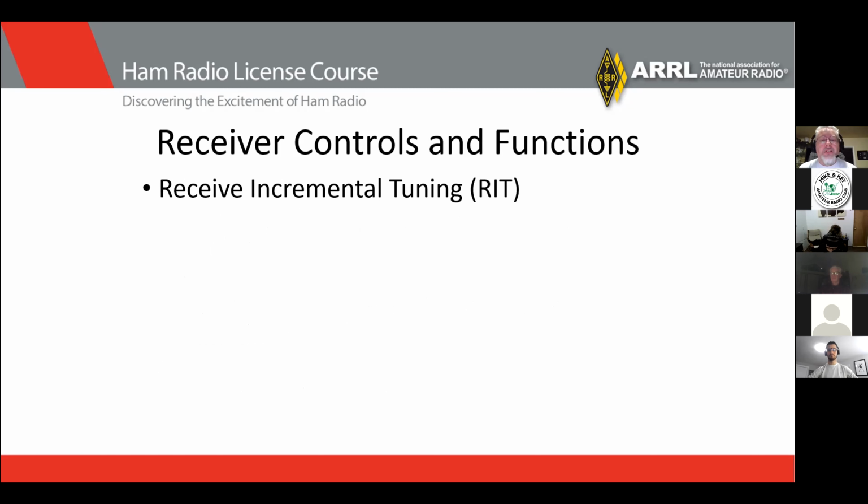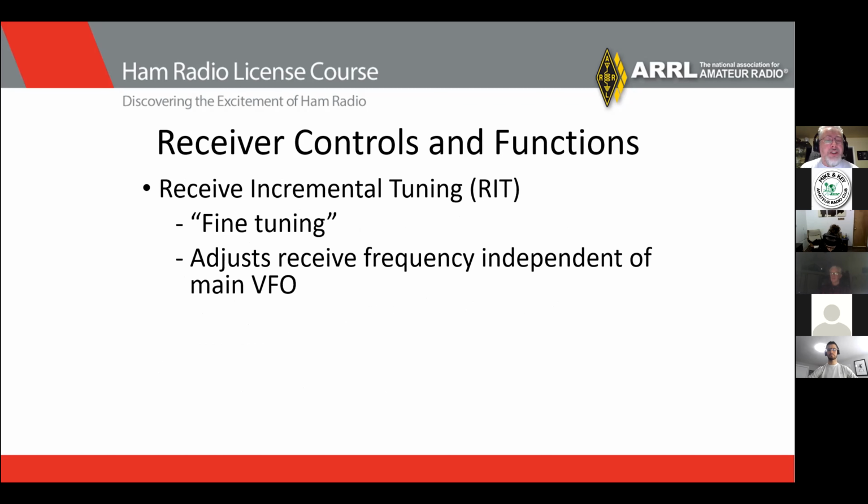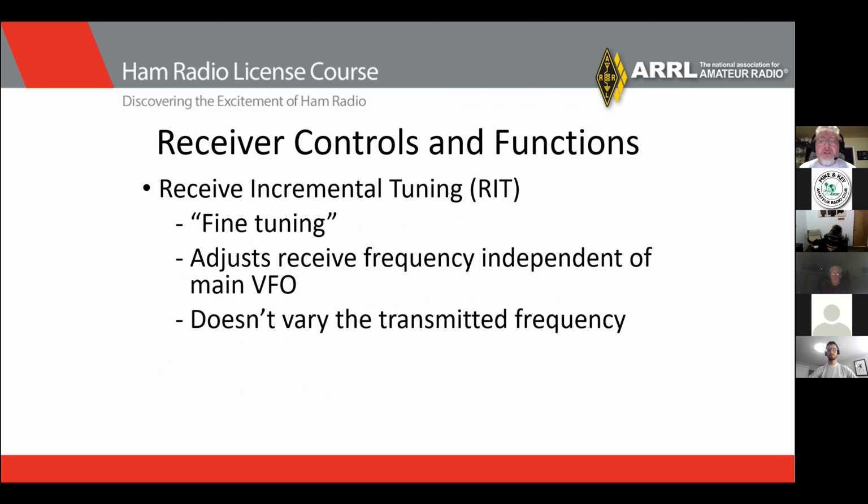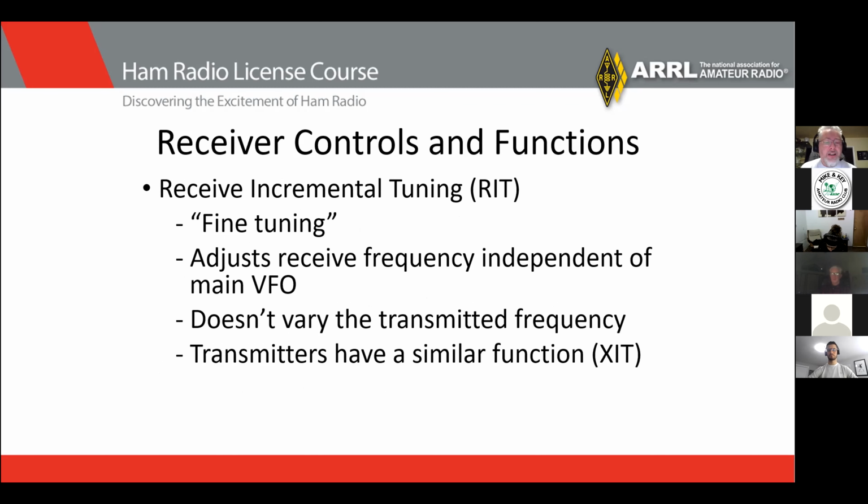Receive incremental tuning, or RIT, is a fine tuning, so to speak, and it adjusts the receive frequency independent of the main tuning dial or the main VFO. But it doesn't vary the transmitted frequency. There are, however, transmitters that have a similar function called XIT.